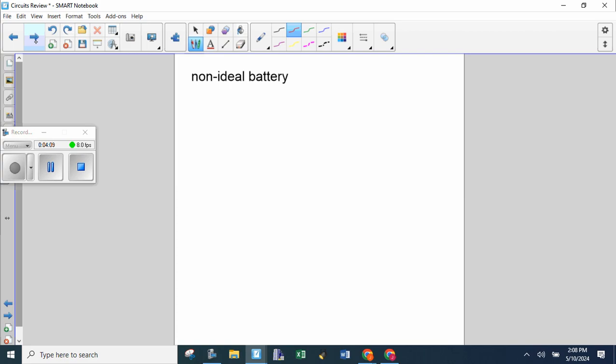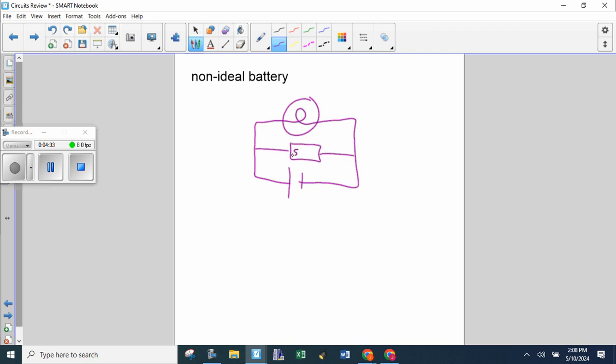And I want you to actually try this with your car. If you have the lights on in your car, imagine the lights are connected to the battery, right? So if you turn the lights on, they will run at full 12 volts or whatever the battery is, and everything is great. And everything else, let's say the starter of your vehicle, is connected in parallel, so it's also going to get the full 12 volts. What I find really interesting, you can see this happening in real time. If you turn the lights on, and I'll just put a switch here, this is your key going into the keyhole, and you close that switch, and you start engaging the starter, okay? Have you ever seen somebody with their lights on who starts their vehicle?